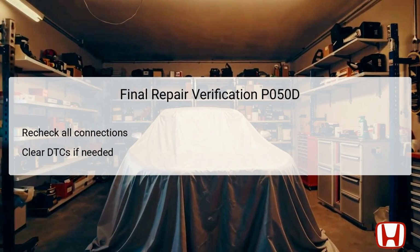In the final repair verification phase, it is essential to ensure that all connections and components checked during troubleshooting are secure and functioning correctly. A successful repair relies on the integrity of these connections, as loose or poor connections can reintroduce the cold start idle speed problem. If necessary, utilize the HDS to clear any remaining DTCs from the system once repairs have been conducted.